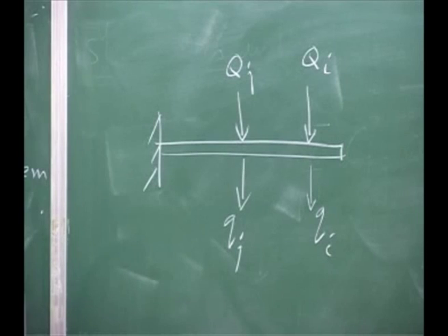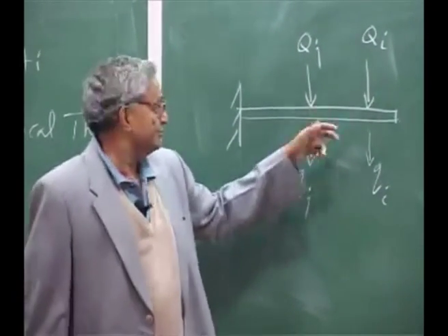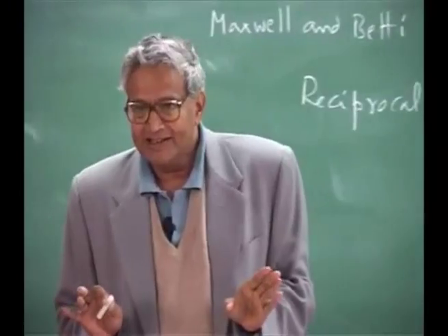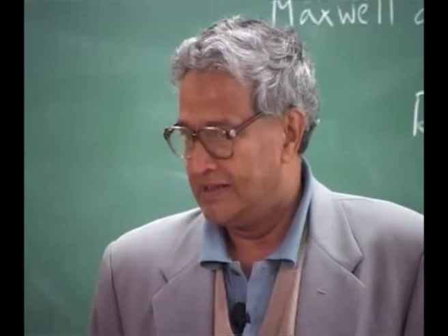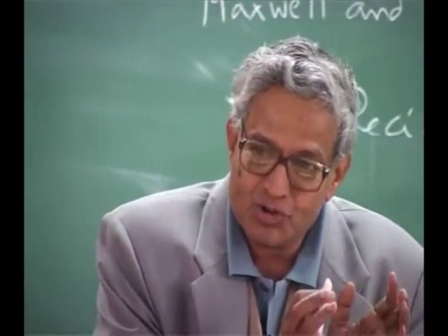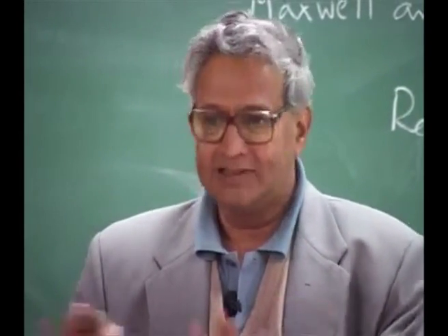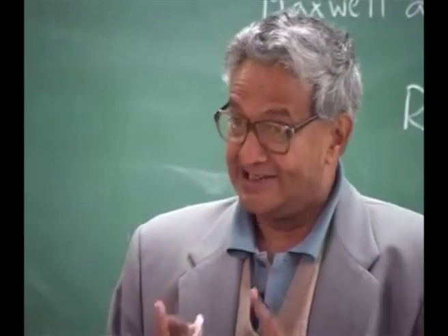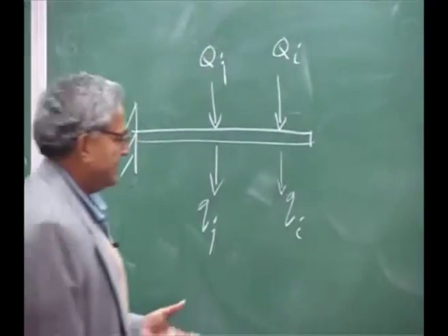Now, in which sequence are they applied? Whether you apply this first and then this, or you apply this first and then this, in terms of the final deformation of the structure, you say it is independent of the sequence of loading. That means the energy stored in the structure because of the application of this load really doesn't matter, which one is applied first and which one is applied later. This linearity is very, very important, so we will prove that.